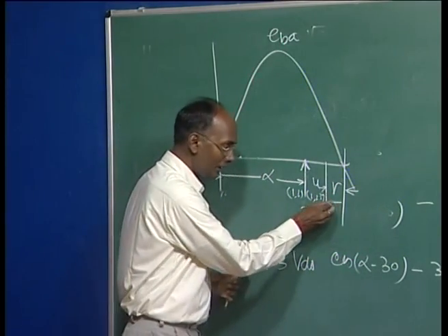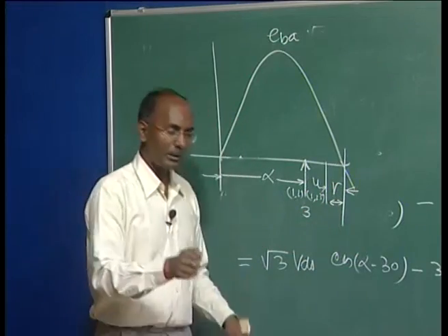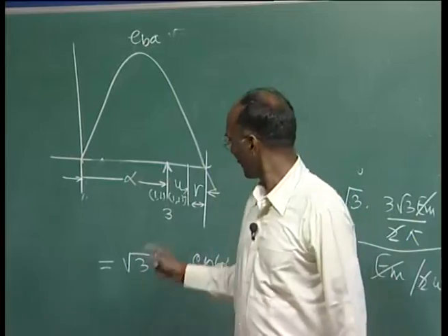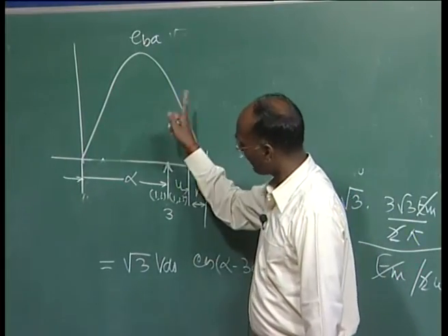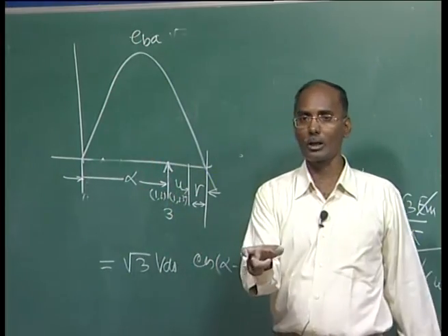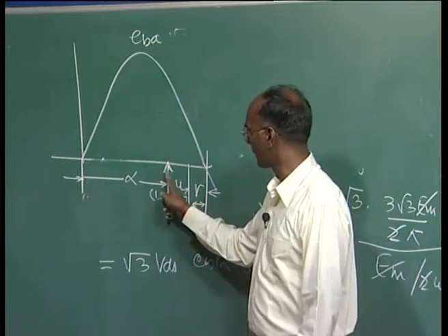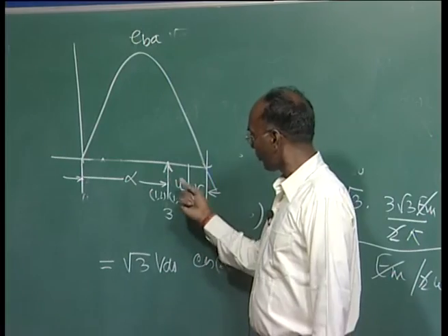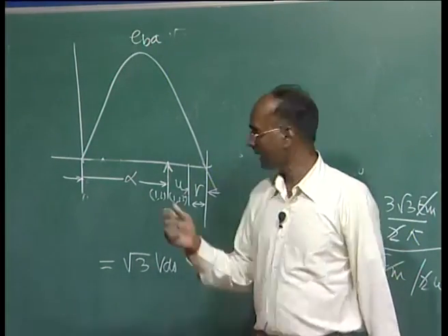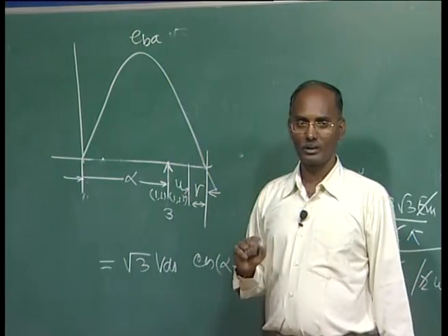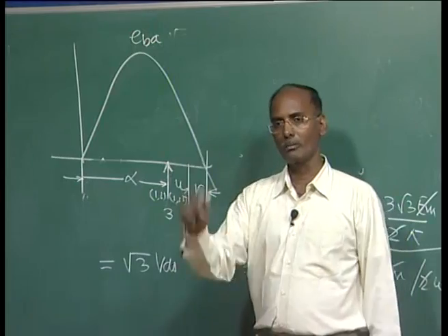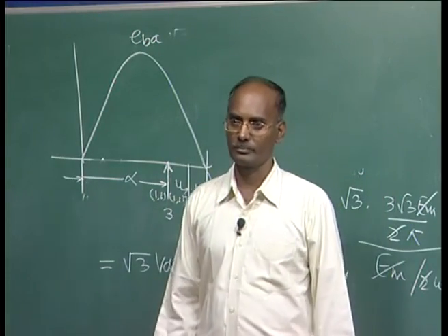To maintain this, we always want to be sure that there is no commutation failure on the inverter side. So, we try to maintain this margin, then we calculate based on the voltage at that time, and then it will be fired. That is, your controller will calculate, and finally it will give the beta pulse. What happens even though you have given the pulse to valve 3 is that the voltage may change at that time. That is why we maintain this angle. We believe that in that period the commutation will be successful.